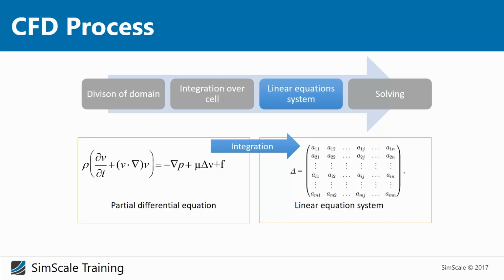And basically, what we're doing in CFD is, if you remember the live demo and the homework we did last week, we are first of all dividing the domain by creating the mesh. Then we are integrating over the cell, which just gives us a linear equation system, which we are solving iteratively. And this is, at the end of the day, the idea and process of CFD. And this is a process which is similar for most simulation techniques.